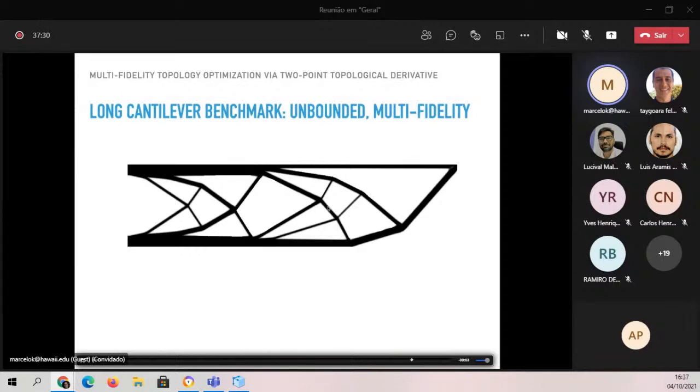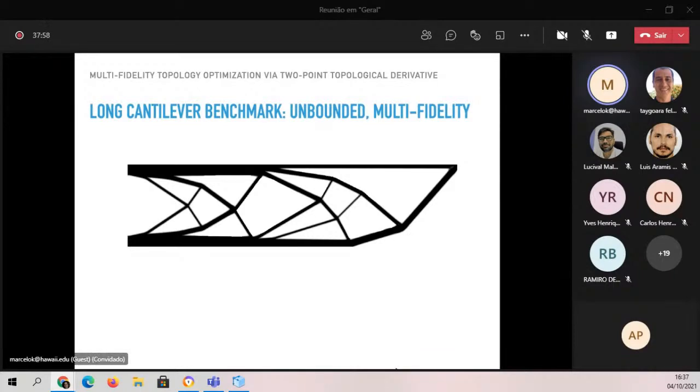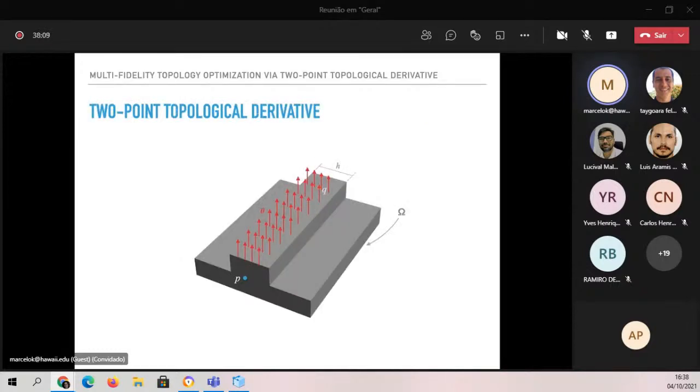Because SIMP is a terrible shape optimizer, because it changes the shape by changing each individual pixel in the picture, which is a terrible way to do it. So here, you see, this is just a minor change in the shape. Topology is completely right. It's just a minor change here, but it takes a long time for it to be able to do that. Okay, so we do better than SIMP. We can do better than level set, and we can do not only better, but also faster than this method. So, okay, that was for the benchmarks.